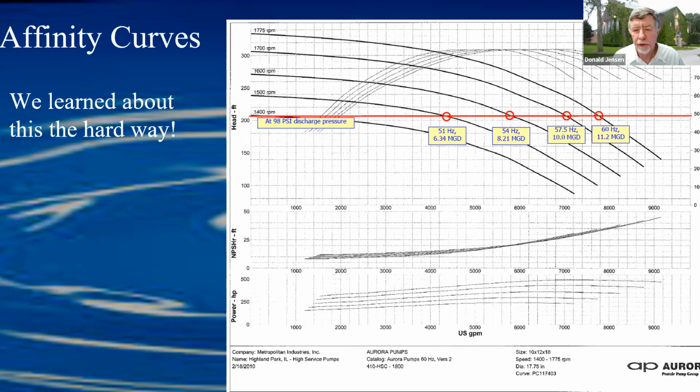An operator would be operating a VFD pump and producing water along with one of the across the line guys. And as system demand slackened off, or someone closed a valve to fill one of the system reservoirs, our customers' reservoirs, we would experience an increase in pressure, and found that the VFD pump was not only not producing water, it was actually forcing water through it backwards. When he turned the pump off, the station flow increased with the remaining across the line pump.